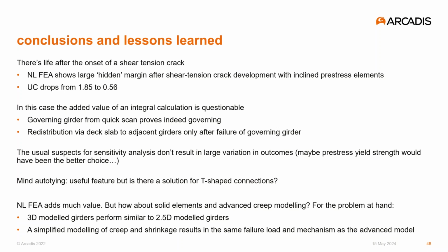And finally, we used 3-dimensional elements to model the governing girder and used an advanced way of calculating creep and shrinkage through time. But in our case, the solid and shell parts behaved in a similar way. Does this mean that I won't use solids for this kind of analysis anymore? Not really. It fully depends on the situation at hand.